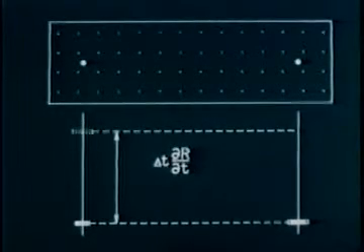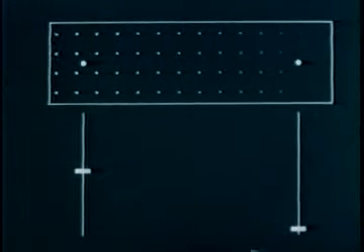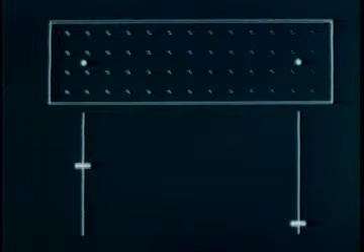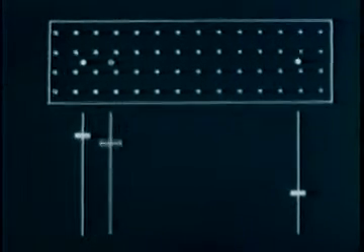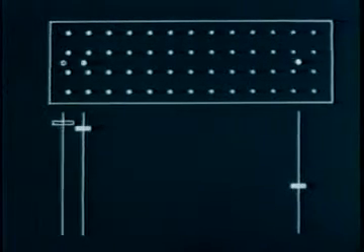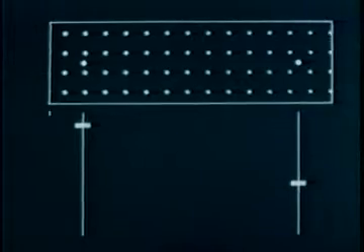Suppose now, however, that the tracer is not uniformly distributed in the river, but that the intensity is greater upstream. Now the intensity at the downstream point is initially lower, and of course both are decreasing with time as before. Just as before, the only change experienced by the material point is due to decay. The change seen at a laboratory point is not, however, since new material of originally higher intensity is being swept past. To express the change experienced by a material point in Eulerian variables, we need two terms: the change of intensity with time at a fixed point and the intensity difference between laboratory points at a fixed time.